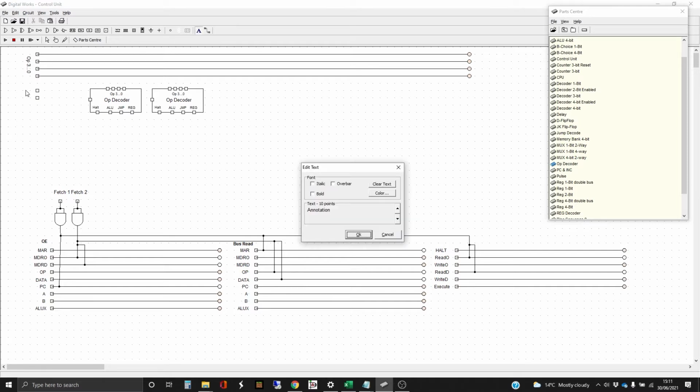And x1. So these are the inputs that come from the ring sequence. X2. There are 4 that we take in, which is the x1, x2, and the fetch 1, fetch 2. Those 2 happen first, and they bring the instruction from the memory and stick it in the op register, which will be connected to here. Okay.